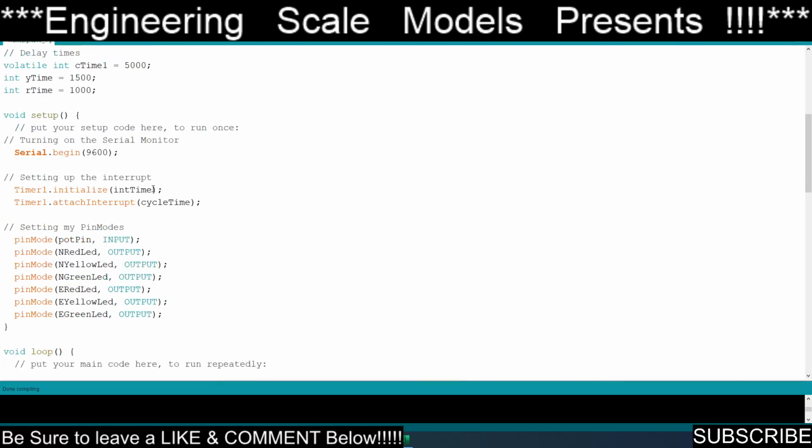So that's my interrupt time. And then you need Timer1 attach interrupt, and then you put the name of the function that you are going to call every time it interrupts. So every 10 milliseconds, it's going to interrupt and run cycle time. Every time that interval goes by, whatever you set your interrupt time for, it's going to interrupt and run this program here.